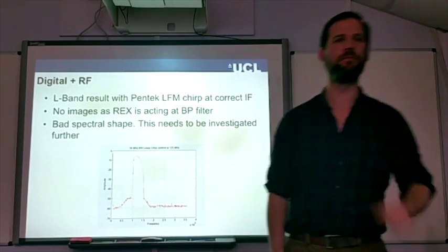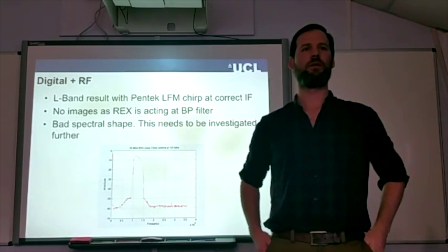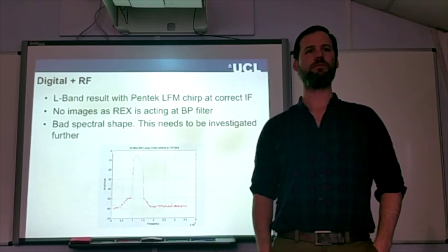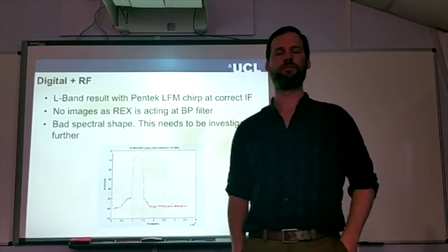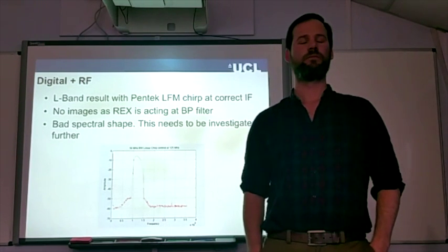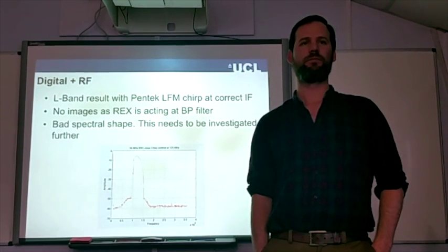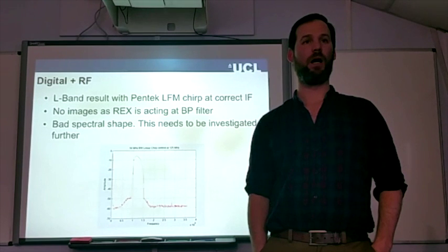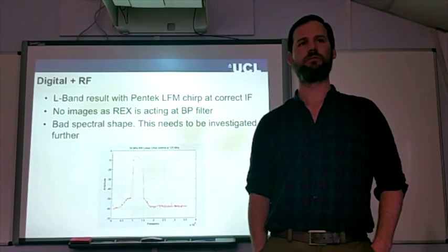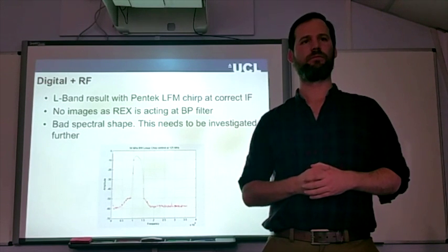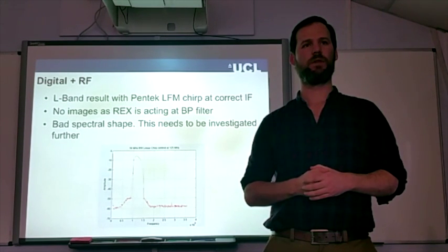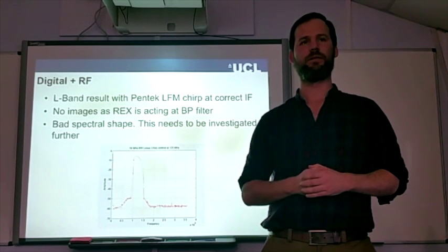Have you measured the characteristic of individual components, the PA, in the gain? You check how flat the gain is, the filter, what the response of these filters. So I think you need to measure each single component of the system, especially at high power level. Yeah. Because a low power signal and a high power signal, the device will behave in a different ball game. Yeah. The temperature, basically the temperature.